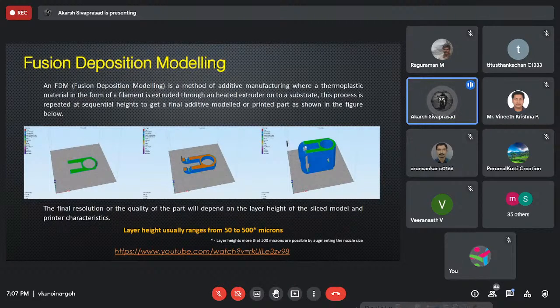And then you extrude that over a path, which is directed by G-code, which is a derivative of the slice that you took from the CAD model. And then you do that for every layer to end up getting a final part. If you see the images, the one on the left is the first or base layer that you plot on the build platform.